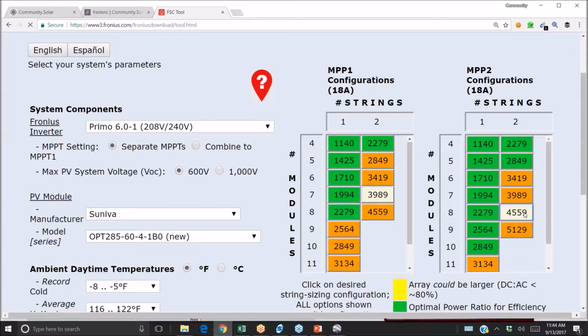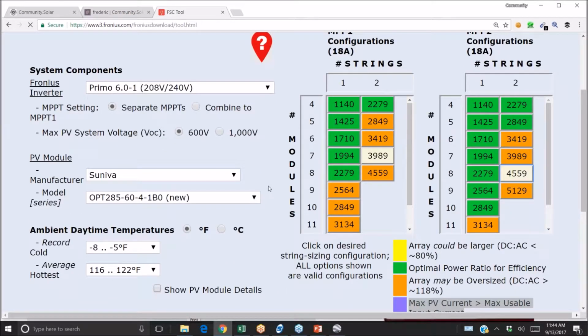But if I had 29 modules on the rooftop, that would be much more difficult to hone in on. And it might be that based off my string sizing, if I'm doing a nice aesthetic rectangular array, based off my circuits and my array, I have to remove a module from the system to get the circuits to work.